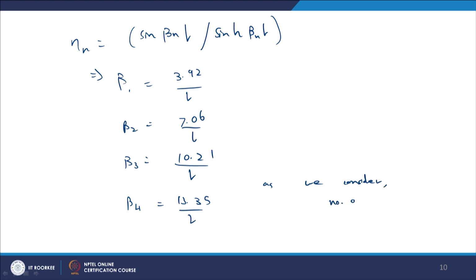As we consider the number of modes here as 4, what are modes? What will modes do? If the mode is 1, the flexible link will have the flexibility like this, for example. If the mode is 4, we have more flexibility of the link. This is the difference between modes. If you have more modes, we have more flexibility of the concerned link. If you have a single mode, the flexibility is reduced.